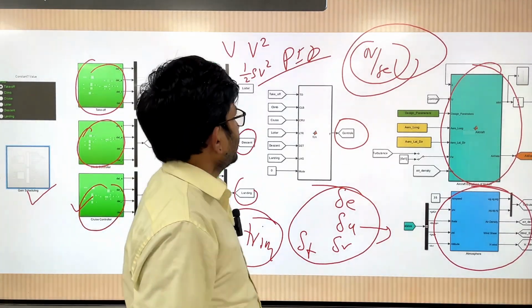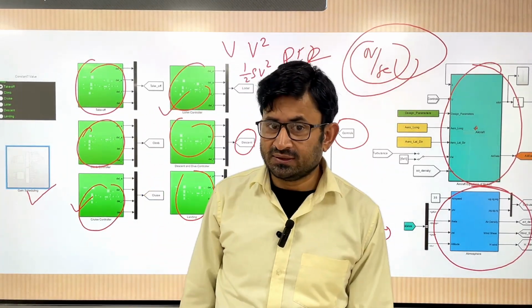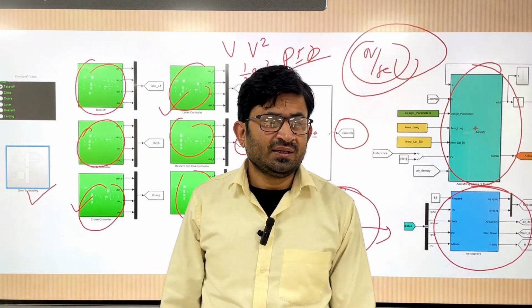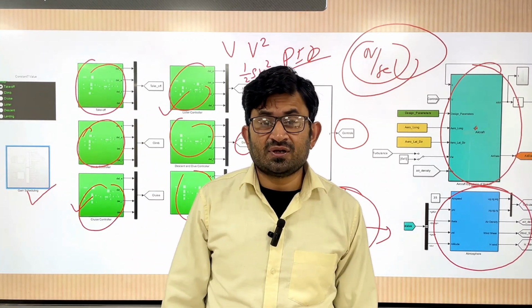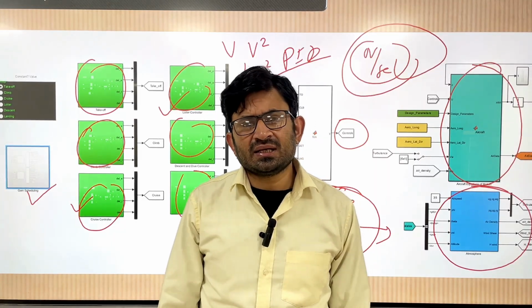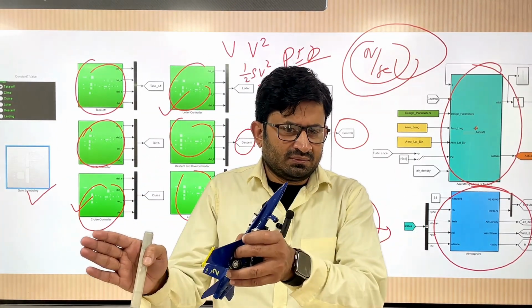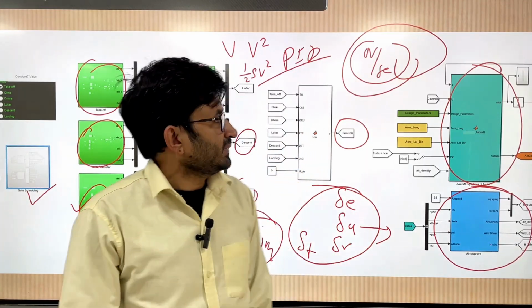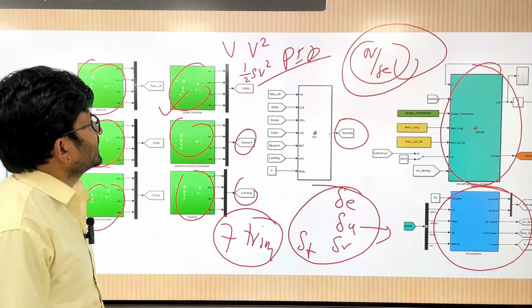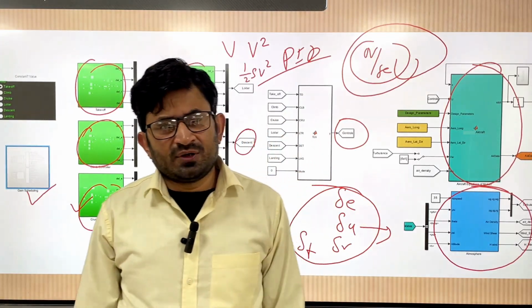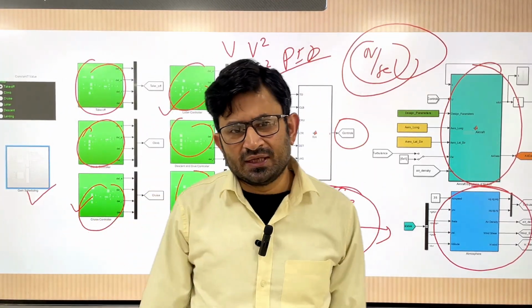So for other trim points, you can schedule the gain based on these three logics: speed, speed square, and dynamic pressure. Why these three? For example, if the aircraft is not highly non-linear, then a single controller gain will work, but with different performance at a different trim point. But if you want consistent performance, you can use speed or speed square. And when the model is highly non-linear, you should take dynamic pressure.